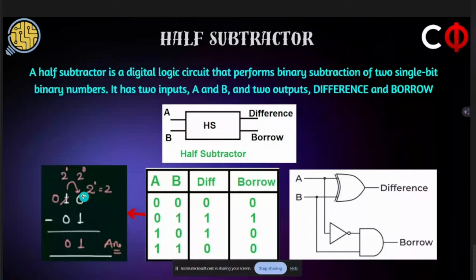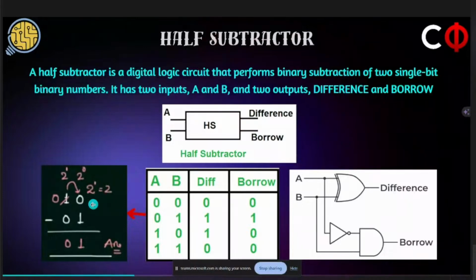So this 0 now becomes 2. So 2 minus 1, you get the difference as 1, and you took a borrow as 1. That is why when you subtract 1 from 0, the difference is 1 and borrow is 1. Because when you take a borrow 1, this 0 becomes 2, and 2 minus 1, difference is 1. Okay, 1 minus 0, difference is 1, borrow is 0, obvious. 1 minus 1, difference is 0, borrow is 0, also obvious. So this is the half subtractor circuit. Very simple. I'll move on with full subtractor.